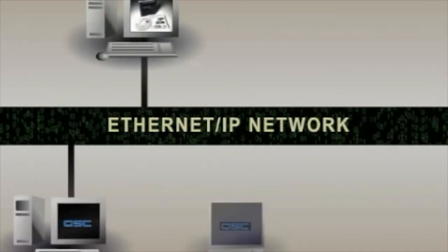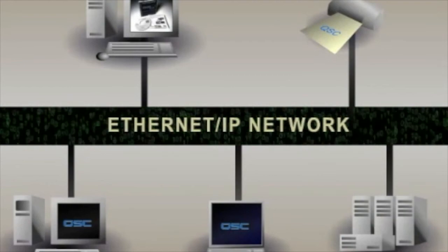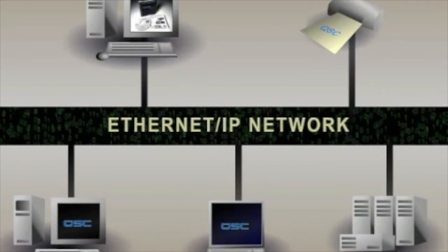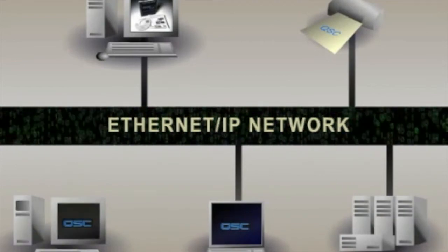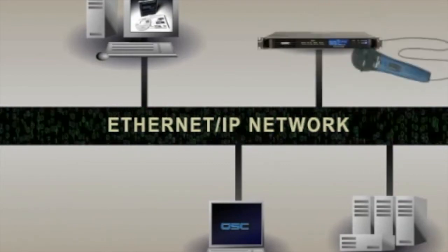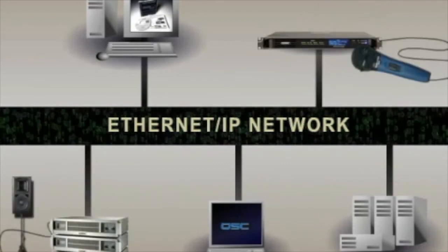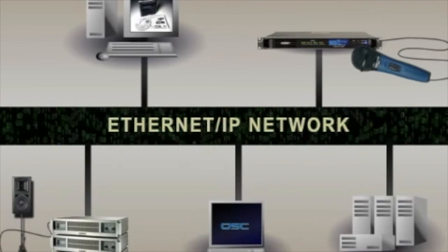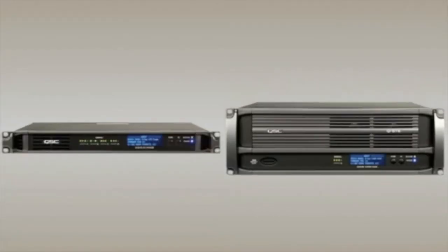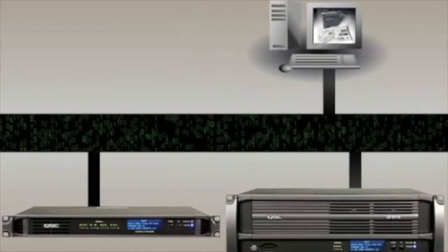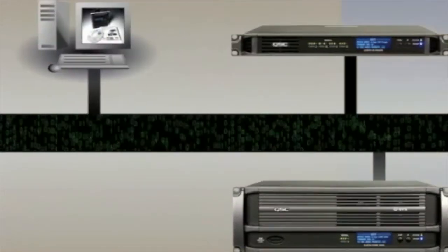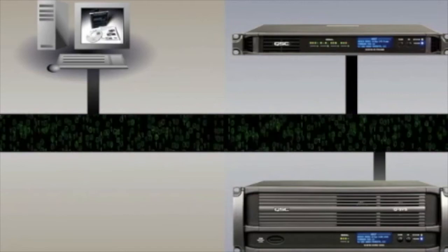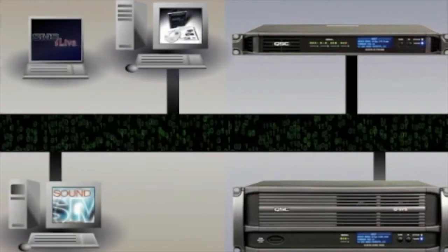The continual influence of the computer networking world on the audio industry has produced IP-based digital signal processors. This allows the audio DSP to be placed on a computer network and function as a network device. IP-based DSP units feature monitor and control capability across the computer network and from remote locations by way of the Internet.